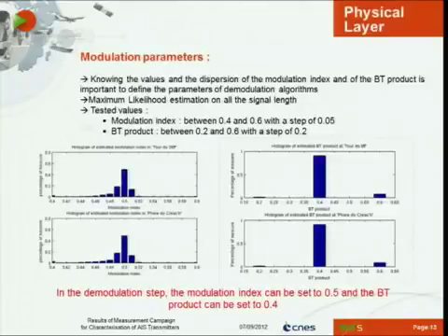So first, the modulation parameters. Knowing the values and the dispersion of the modulation index and the BT product is important to define these parameters in the demodulation algorithms. So we estimated these parameters thanks to the maximum likelihood estimations on all the signal lengths.